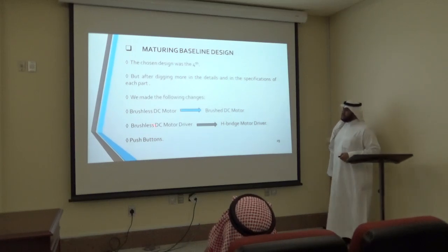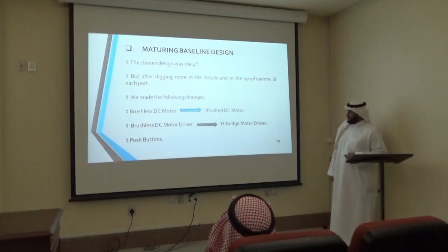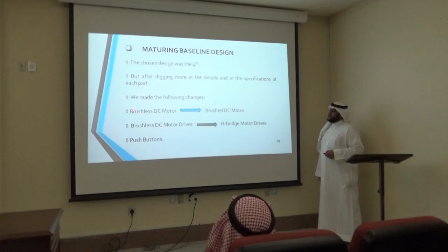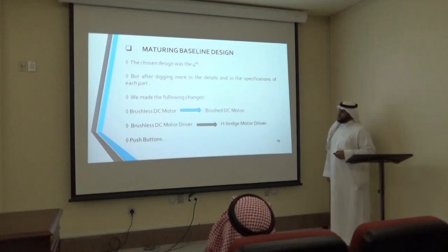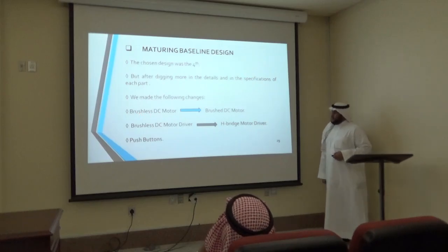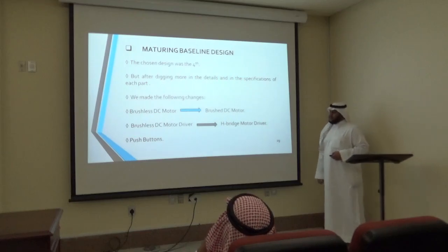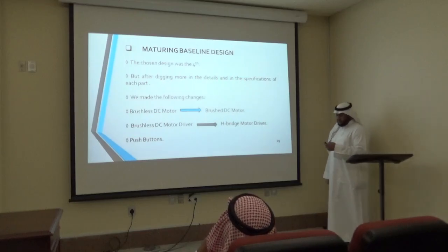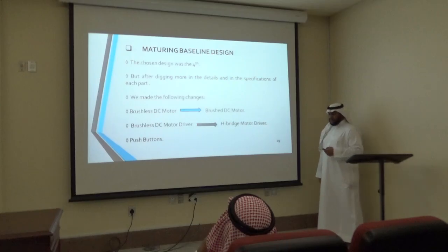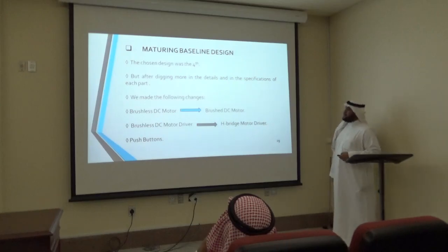The second change is the brushless DC motor driver. We changed it to an H-bridge motor driver. Since we changed the DC motor from brushless to brushed, we have to change the driver also. Also, we have to add push buttons to implement the manual override option in our project.